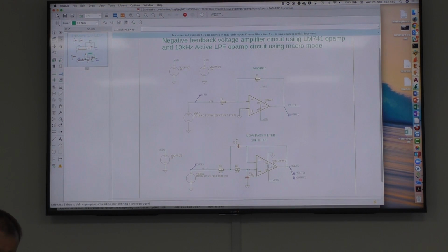that's an example. If you draw your schematic and you want to do simulation, you have to add a SPICE model. We have a library for diodes, resistors, and so on, so there are some models already assigned. And then I have to place some probes. What do I want to know? I would like to know the voltage, the phase, what's happening in the signal. And that's what we have here.